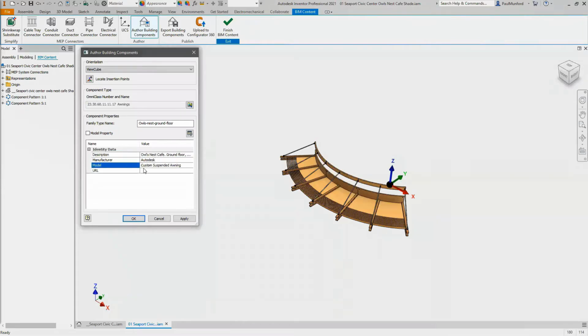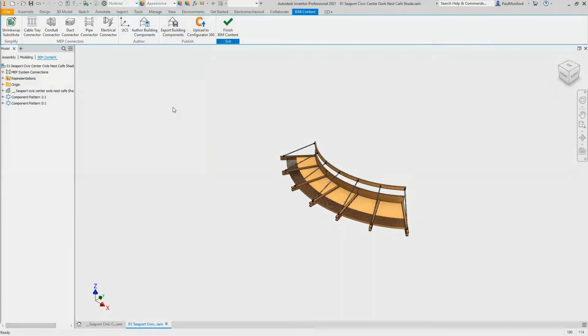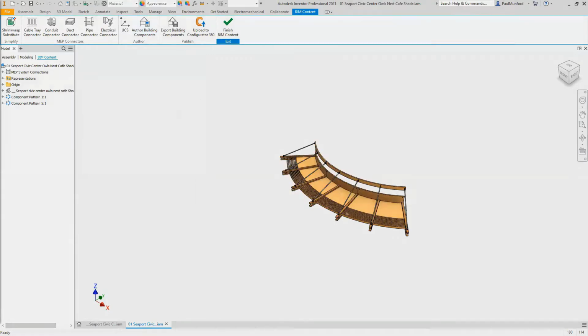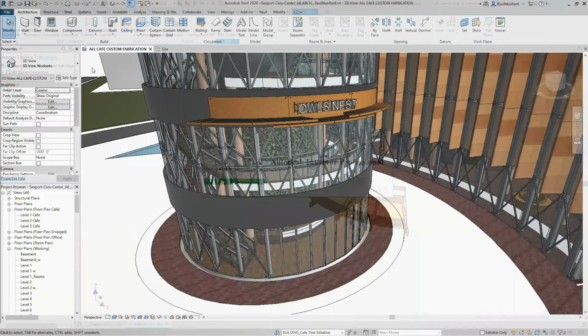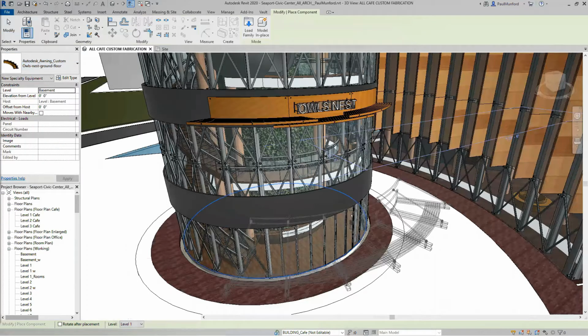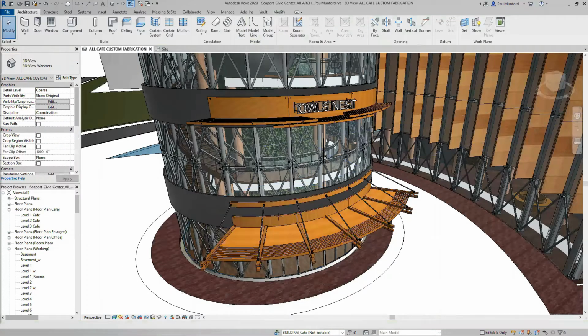When your design is ready, you can output your model from Inventor as a BIM object, ready to submit, closing the loop on your design cycle. Now, Inventor 2021 has extended that AnyCAD functionality to help manufacturers in the construction industry collaborate and coordinate on your BIM projects.